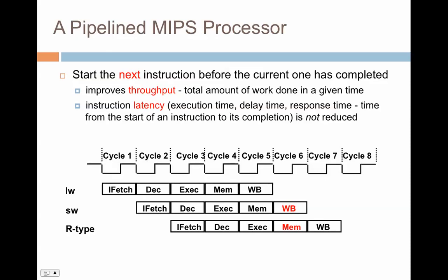In cycle 4, that address is sent to the data memory to access your word. And that word is then written in the write back stage to the register file. So the load word is an instruction that would take 5 clock cycles to complete. And this would be identical to what would happen in a single cycle data path and control, except that between cycle 1 and cycle 2, we are going to put some latches where the signals are going to stall for every cycle.